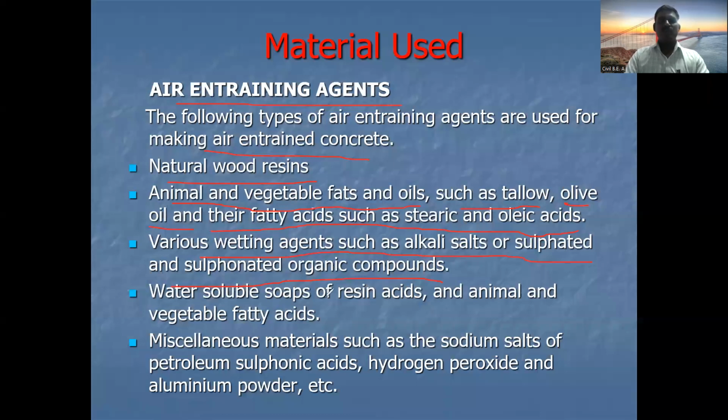Then the water soluble soap of the resin acids and animal and vegetable fatty acids is also used to increase the entrained air in the concrete, up to 8%. So this is related to the materials we are using.